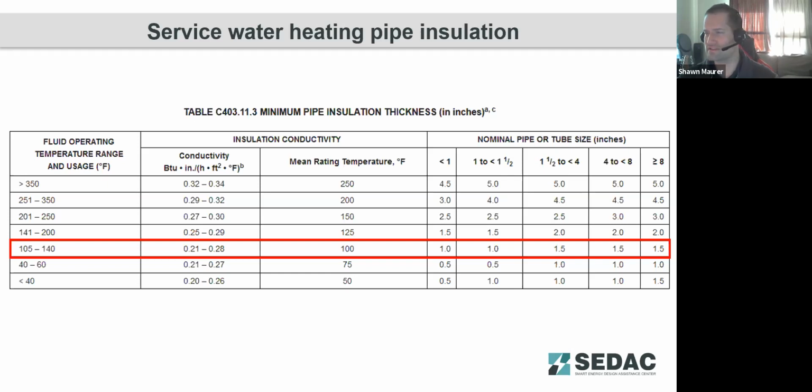And also increased insulation, especially since the Energy Code for most service water systems is going to require some kind of circulation system in order to maintain a heat source close enough to your fixture that you get ready access to hot water.